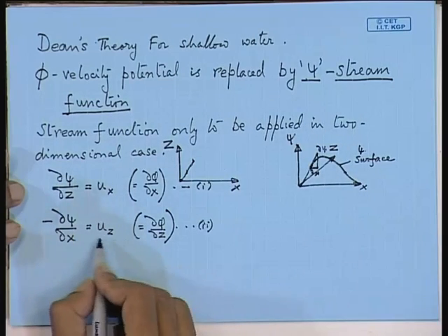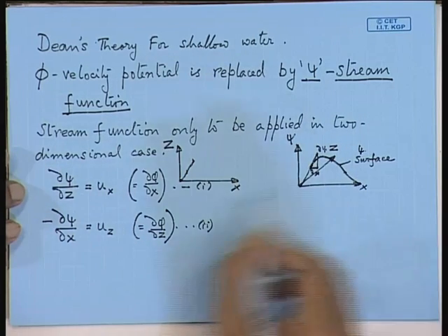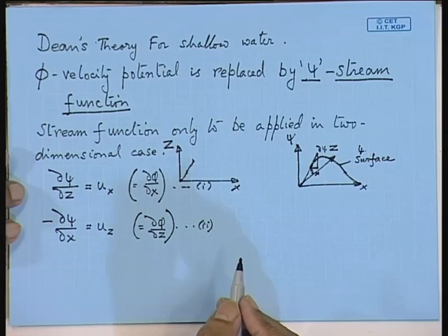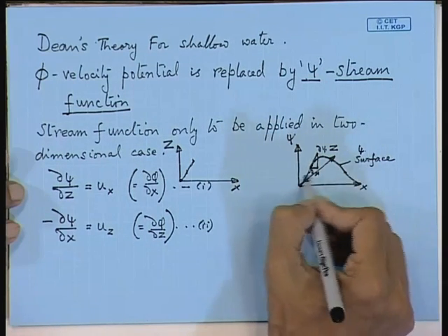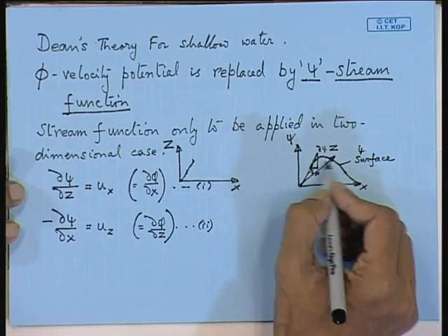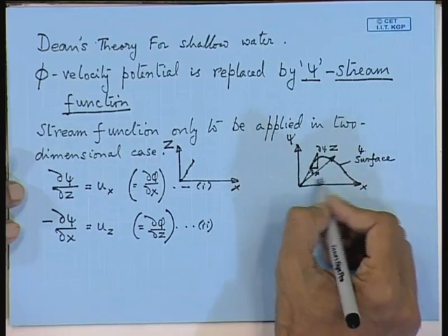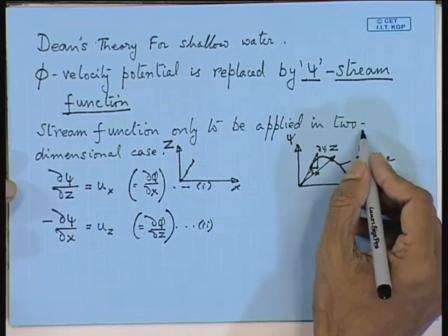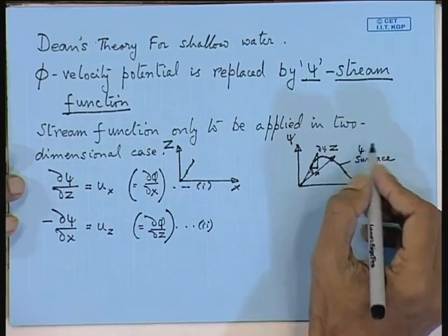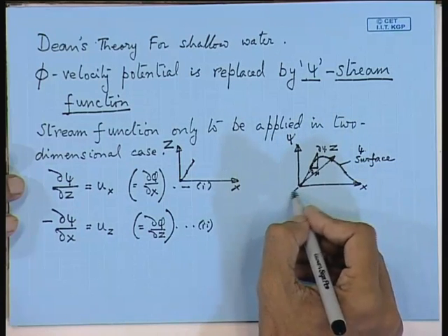So, what we are getting is the slope of the psi surface. So, here actually you will get the velocity. Now, velocity will be in what direction? You find out the slope from the psi surface contour, and from the slope you will get the velocity, not in this direction. Now, the z direction is going inside the blackboard. So, we will get it in the opposite direction.